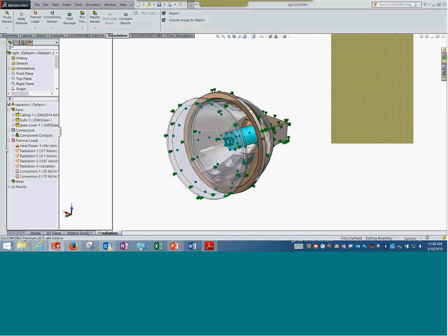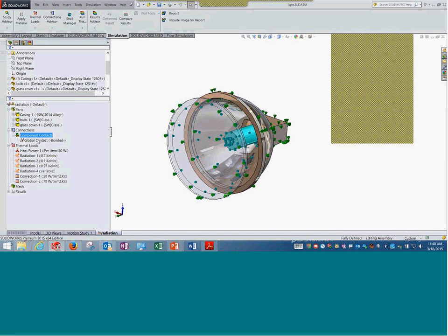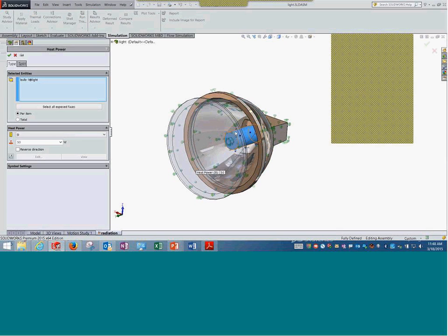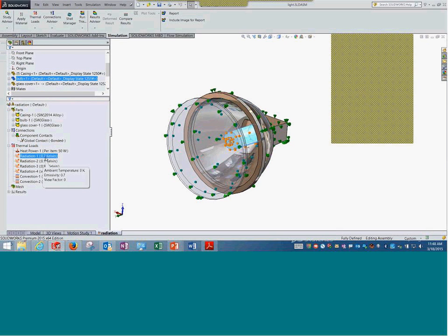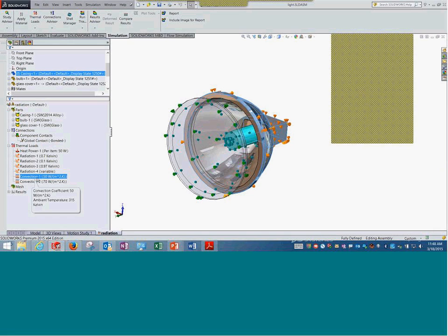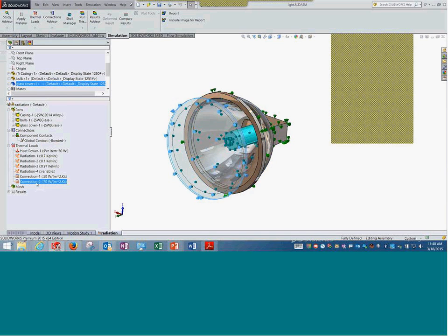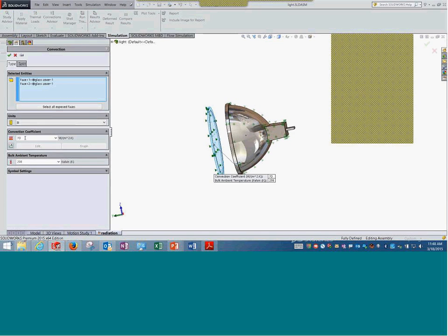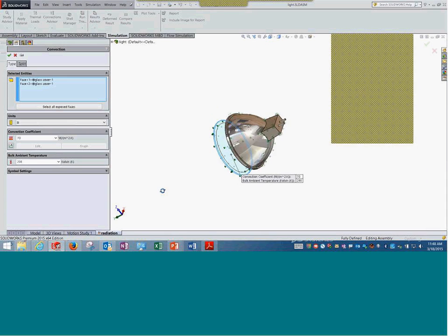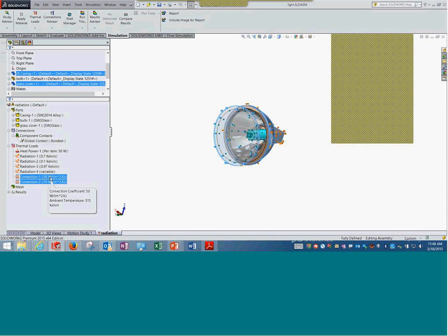Most properties all remain the same. The type of study that you create is the same. It is a steady state study. You are telling a certain component to be creating the heat. Now, first of all, this lamp is exposed to the atmosphere. So we specify convection on exposed surfaces, telling the heat it can dissipate to the atmosphere through those exposed surfaces, done by the convection coefficient and by temperature, the atmospheric temperature around the setup. Those two come up over here.